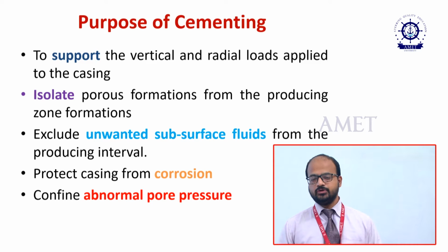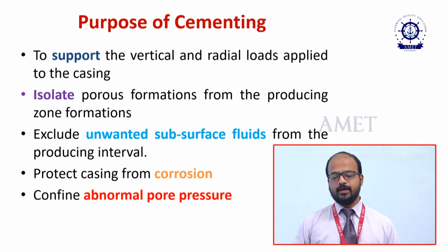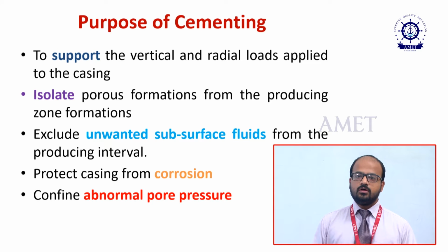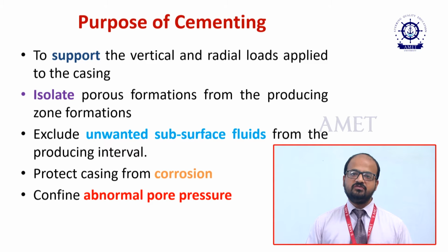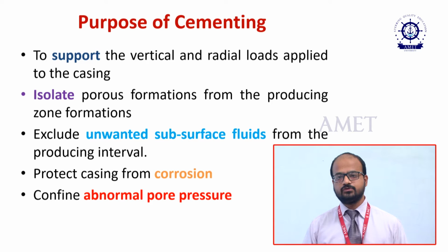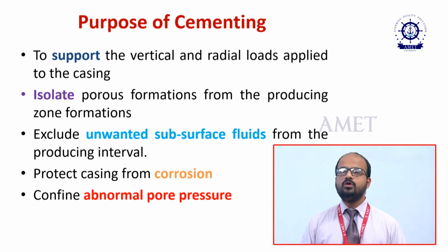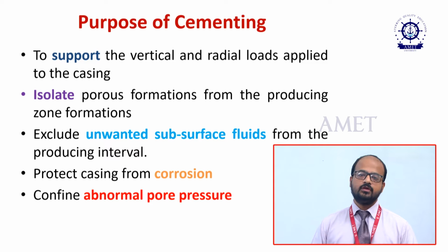Now it is helpful against corrosion. If you go deeper, you will get many environments such as acidic medium and gas medium and some poisonous gases which will create corrosion in your casing pipe. If I want to stop the communication between your casing and these gases coming from the formation, what do I have to do? If I put the cementing, the communication will automatically be stopped.